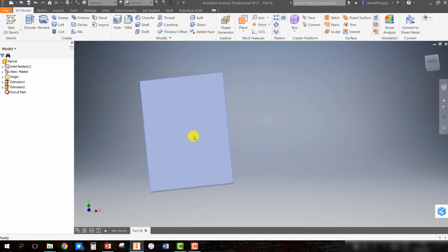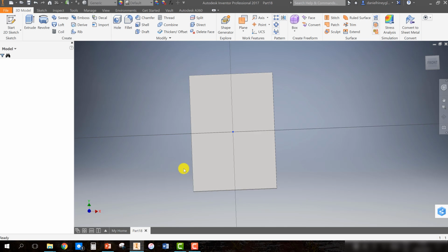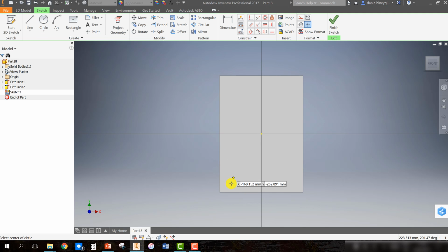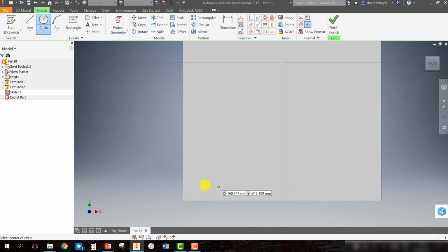Then on the front of the door, we're going to create a new sketch, and we're going to do the 2 holes for our 2 dowel holes, dowel diameter, and that's going to be equal to 4 mil. And we're going to do the same above that, and we're going to let that equal to this one here.